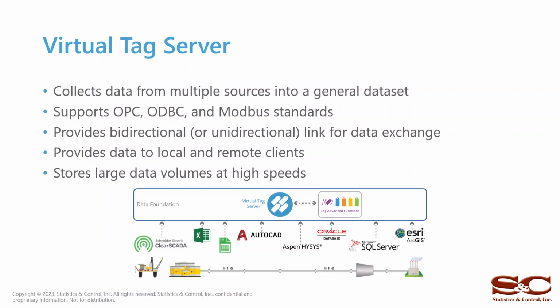And one of the ways that we connect real-time data is through our virtual tag server. So with our system, you build the model and then you simulate what's going on in the process, and then the virtual tag server connects all that live data. So it's getting streaming data from OPC, ODBC, Modbus standards, even web clients as well.